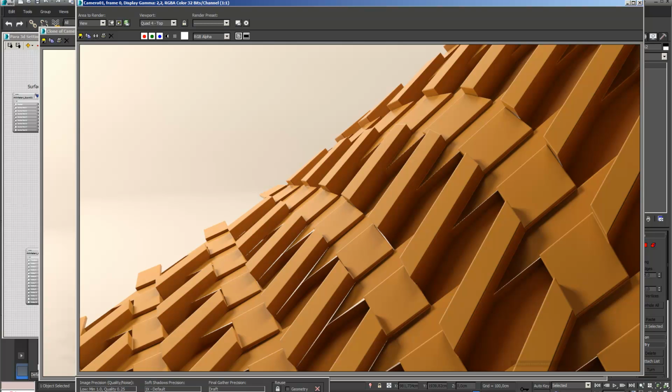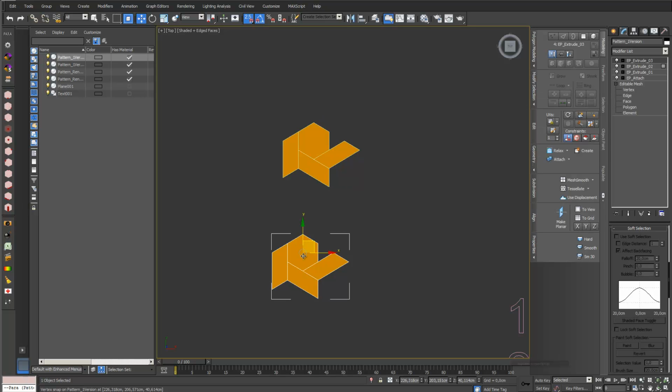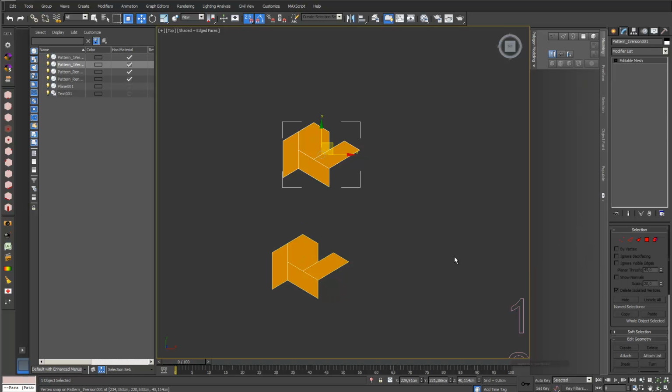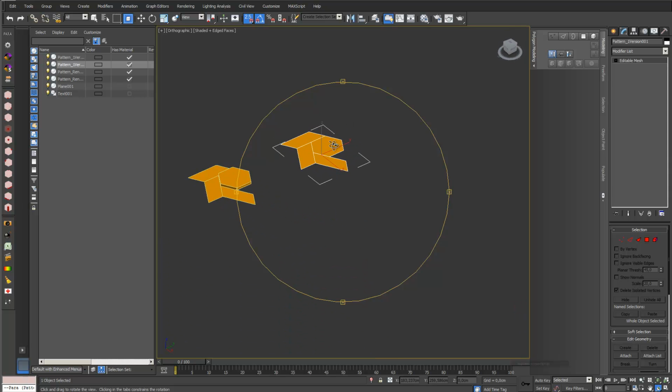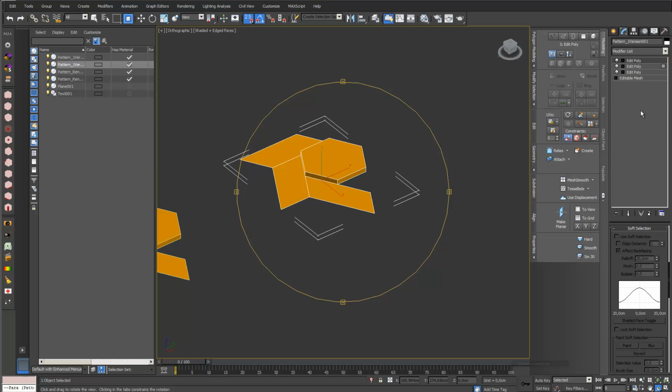And this time you can see that there are still little issues, and they are just related to the basic topology of my pattern. What I can actually do is I can just select my basic polygon. I just copy my edit poly extrude 1, 2 and 3. I just select it with my uppercase key held and right mouse click and copy it. And now I select my object which doesn't have any three-dimensional edit polygons anymore, and I just right mouse click and paste. Okay, and here we go.